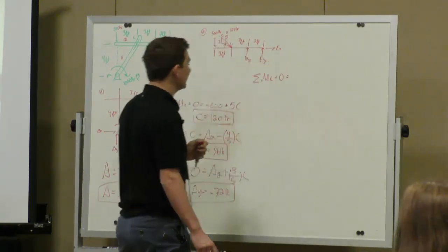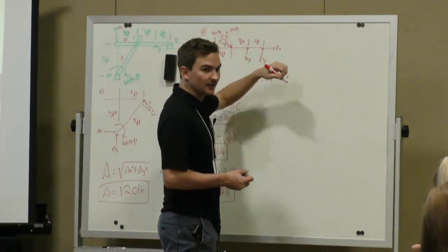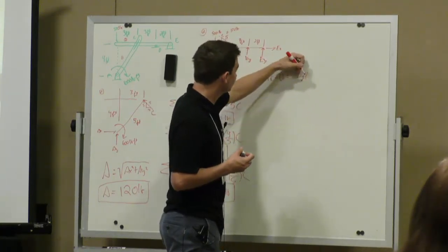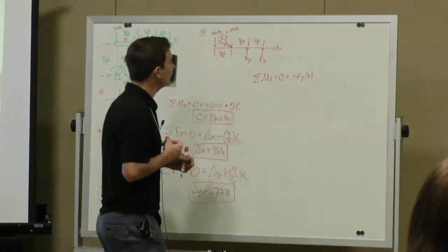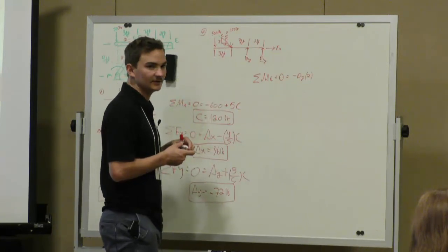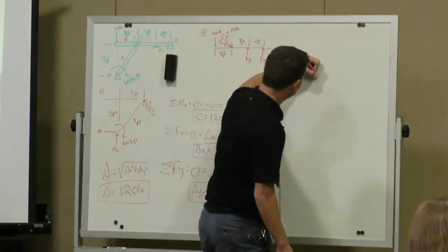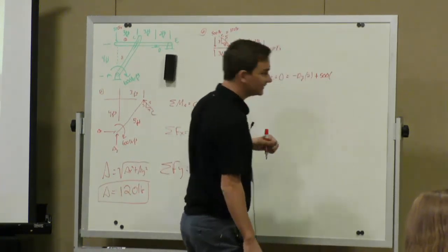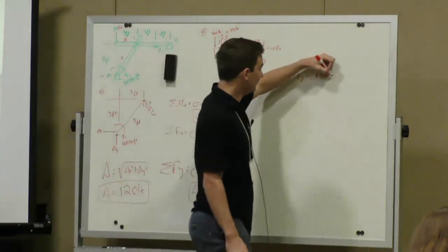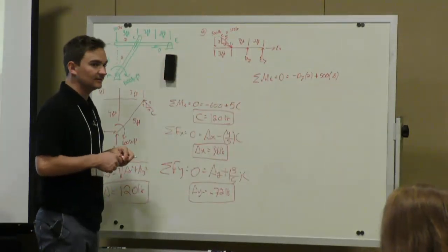So what forces cause a moment about E? DY. What is that in the equation? Is it negative or positive? Negative DY times 2. That's its perpendicular distance, its moment arm. What about, let's skip C and go to the 500 first. Is that a positive or negative moment? So the 500, yeah. It causes a positive moment, very good. Times, what's its perpendicular distance? 8, yeah. So 3 plus 3 plus 2, 8 feet. And now C. How do we take that moment?